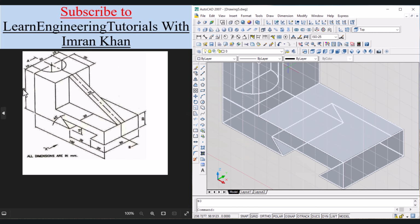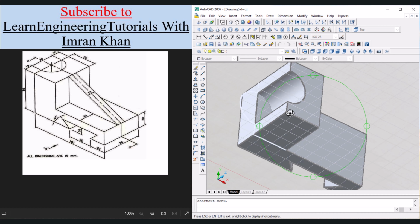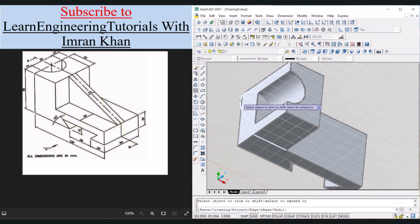Because the total height of this object is 60, 20 is already given in this view, in the front view, so we are left with 40, so that's why we have given 40 value over here. Now use orbit command, so click on this free orbit. Now use trim command, so click on trim, press enter, and click on this semicircle that is removed.